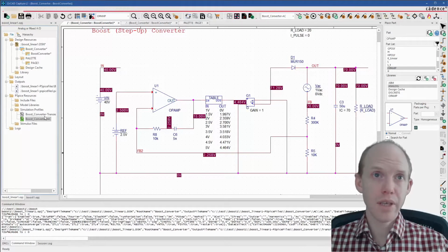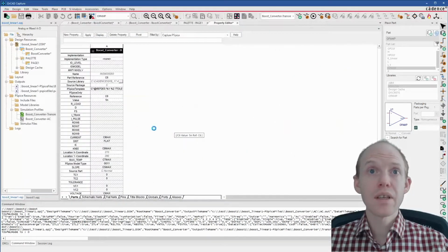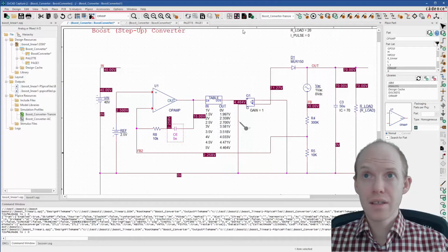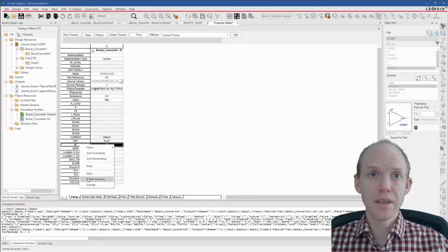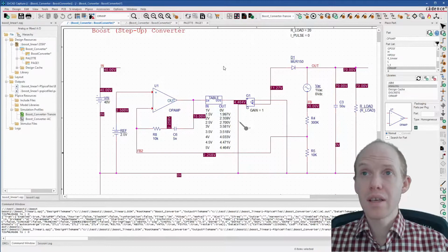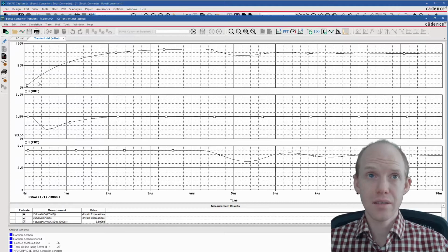So to do this, we want to get back to the transient analysis, and then I think we'll want to start by just checking all of our initial conditions. This guy here has no initial conditions. This guy here, I want to see what happens if we just get rid of this one altogether. So let's delete this 70 volt initial condition and see if this thing will still regulate. Looks like it's decided here to start at 0. That's not what we want. What we want is to have everything start out steady state in this transient, so just everything flat lines.